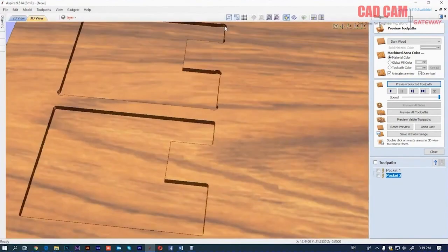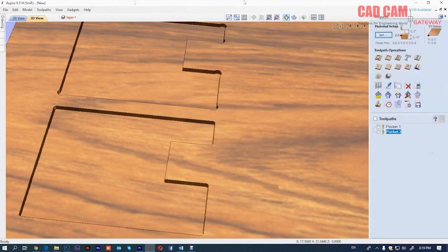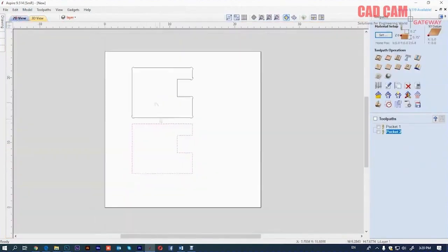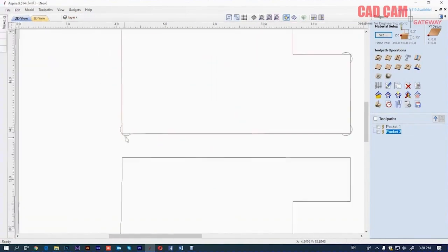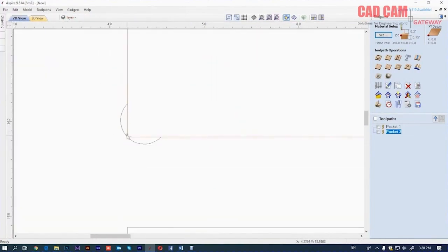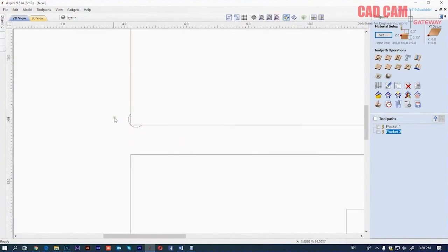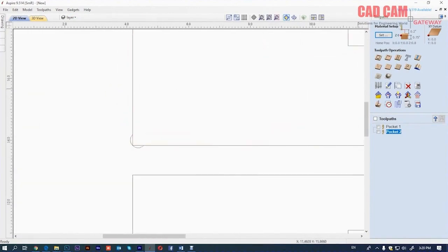On the other hand, with this object, when we apply this fillet or rounding on it, the upper corner will easily insert into it. Actually, the need here is that when we insert a part into this end, it should be able to go in easily, and the corners shouldn't cause any obstruction anywhere. I'm showing you the same thing here. See, the part will fit here easily. That's why this rounding is done, and I hope you've understood this point.